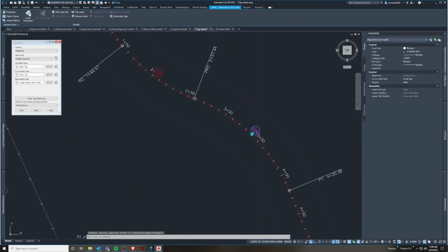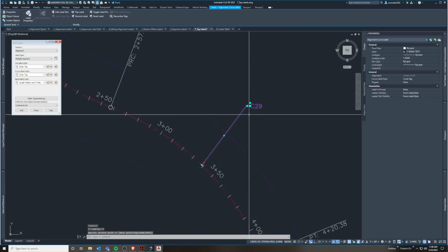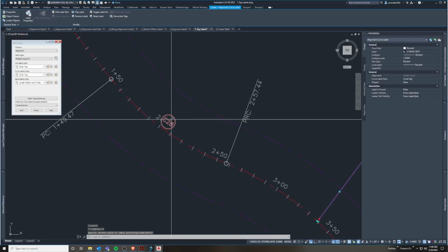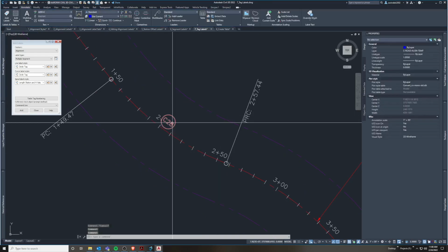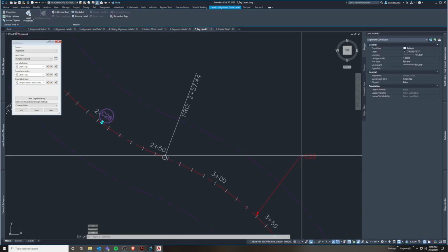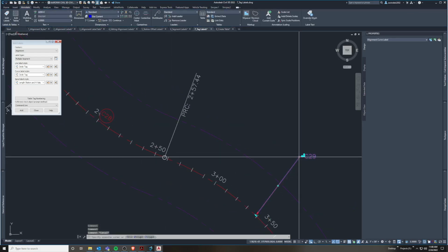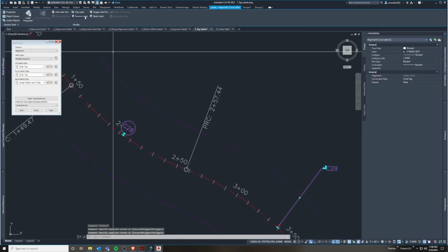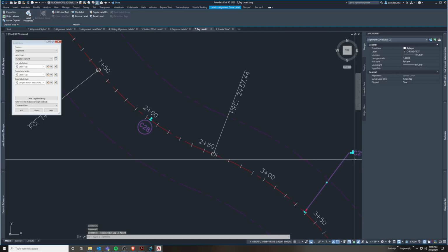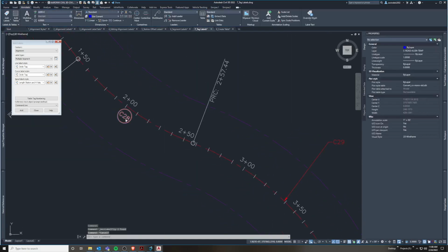And these segments also have grips like this that we've already learned about. You can drag them off, and the drag state looks different, as you notice, than the initial default state. If I get this one just selected, if I hold Control, you don't need to hold Control for these. They're all independent, like the last station offset labels. You could flip both of these. This drag state doesn't flip. So we have our labels. Now we're going to renumber them.